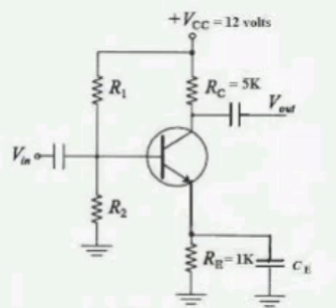Then the feedback of the op amp is 20 kilo ohms, and the output is Vout. So you know that mu n Cox into W by L equal to 0.2 milliamp per volt square. Vt equal to 1 volt. Given Vg is very small. Vgs equal to Vg minus Vs equal to 0 minus of minus 2 equal to 2 volts. Vds equal to Vd minus Vs equal to 4 minus of minus 2 equal to 6 volts. Vds greater than Vgs minus Vt.